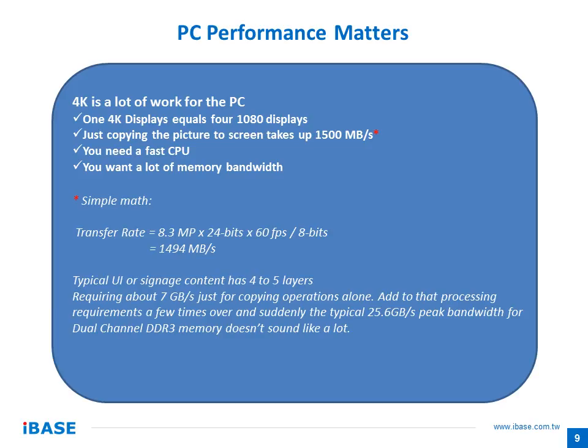You want a fast processor, which means, generally speaking, you want a desktop processor because they go to higher clock speeds. They run their memory at higher speeds. And you want a lot of memory bandwidth. You want the fastest memory bandwidth that you can get. Memory bandwidth really is one of the biggest bottlenecks in digital signage. It really is, in my opinion, a bigger bottleneck than processor performance or anything else.